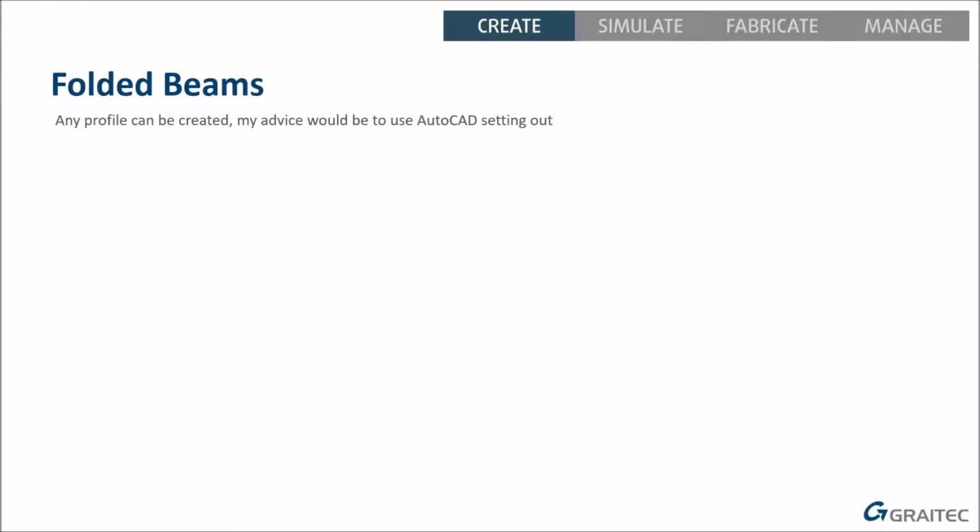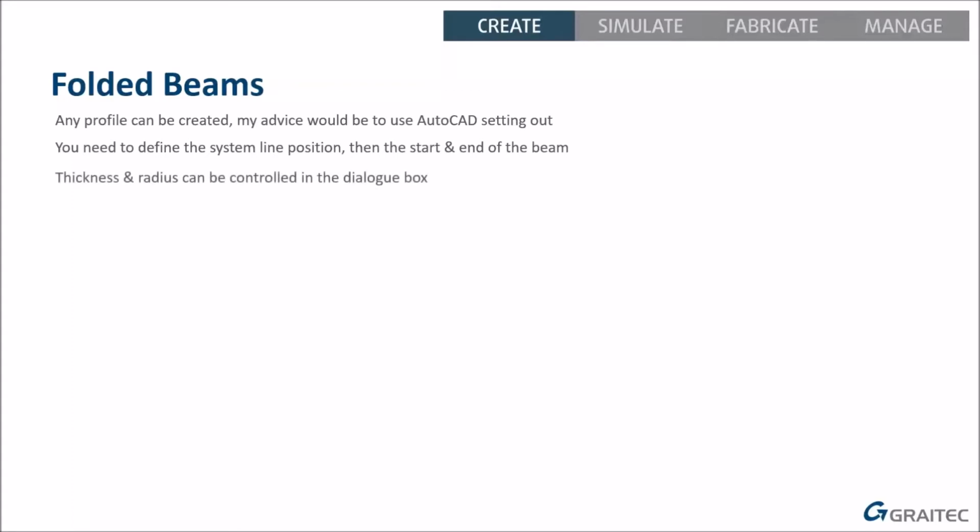With folded beams, you can create any profile. My personal advice would be to use your 2D AutoCAD setting out. So draw out the profile you want and then create the folded beam on top of that. When you're creating it, you do need to define the system line position. That's one input, and then you do the start and the end points for the actual length of your beam. And then your thickness and your radius can be controlled in the dialog box.